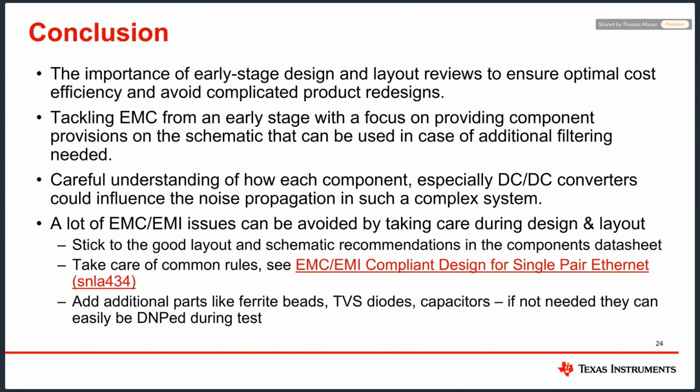On one hand, you can stick to good layout and schematic recommendations, and many times the device data sheet already shows good recommendations. So make sure that you read the layout recommendation part.